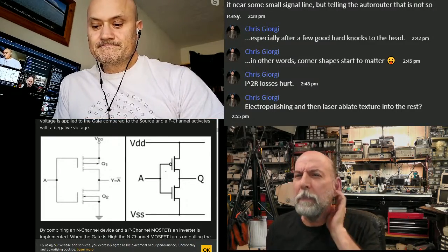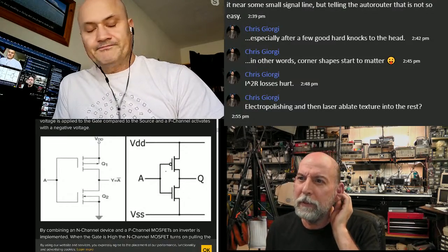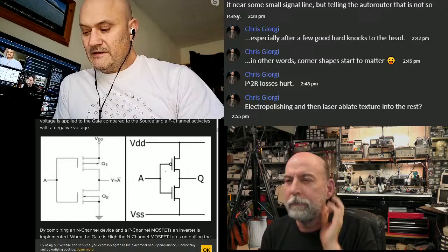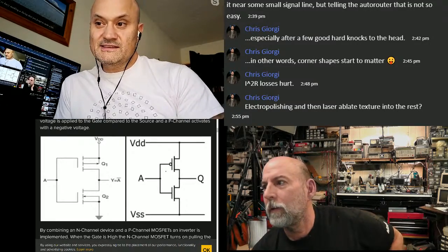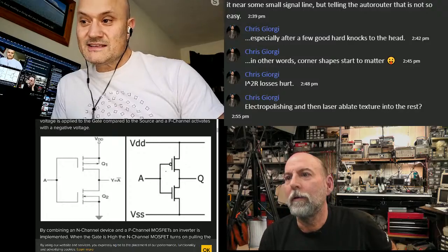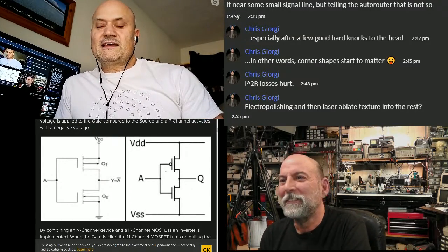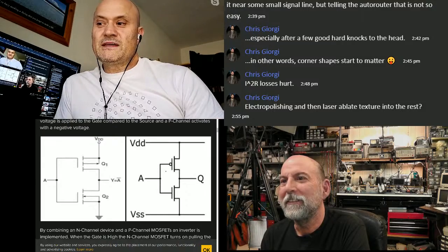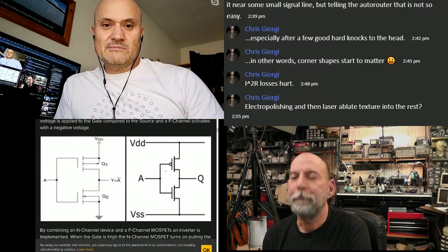What about the PCB manufacturer? Do they complain if they're milling out copper and hitting copper, or are the tools too good? If you make a design note in your drawings and say this is deliberate, yes, this is what I want you to build, then they can't come back and say, we're not sure if you meant for this. Do you realize you've got copper coming off the edge and we're routing past that?